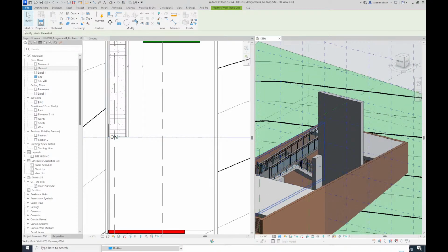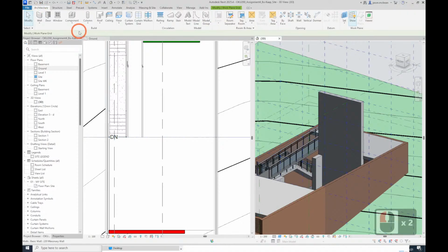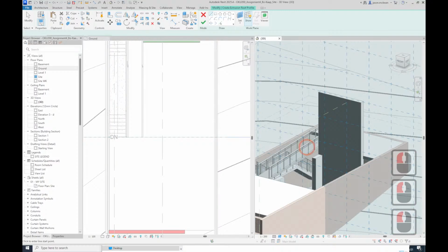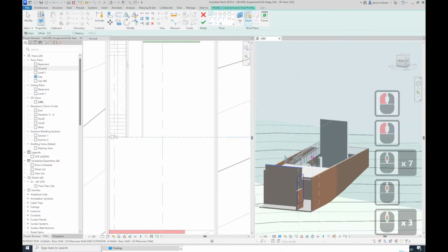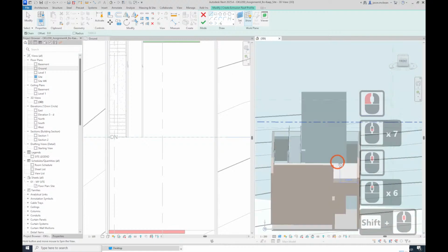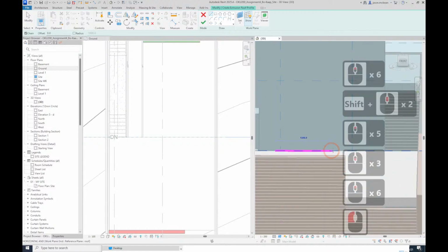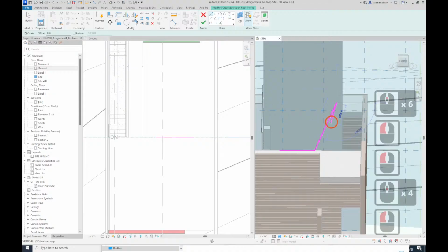based on an extrusion. So I'm going to go to Architecture, and I'm going to say roof by extrusion. So I'm going to tell it ground floor. Yes. Okay, now it's looking for a work plane in which to work. It's actually crazy easy. I'm going to go just like that for now.